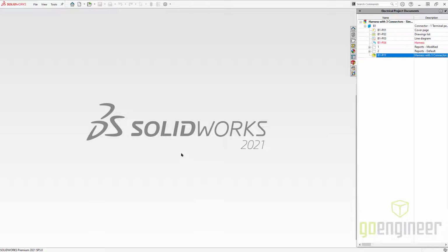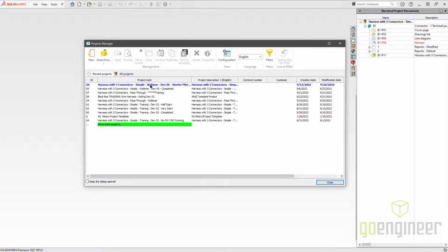If it's only a few parts, that's not that big of a deal. If it's several hundred, that could be time consuming. Duplication sometimes does maintain associations, but keep in mind this is still going to point back towards the same assembly. It's not duplicating the assembly. Again, what I'm referring to here is in the project manager.